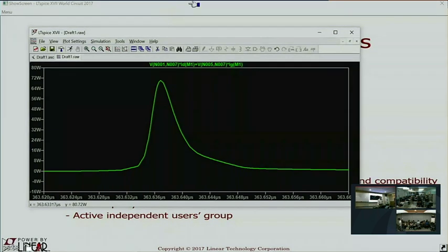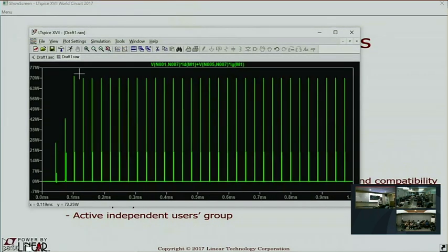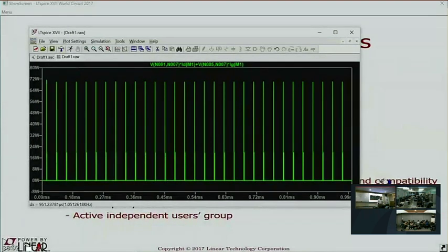So what just happened is I plotted dissipation as a function of time, and I did not find out if it's too much dissipation. I found out that dissipation as a function of time is not what I am interested in. When people say dissipation, what they mean is average dissipation. Average dissipation is the physical quantity that powers a calorimeter. So to find the average dissipation, we have to integrate this waveform.